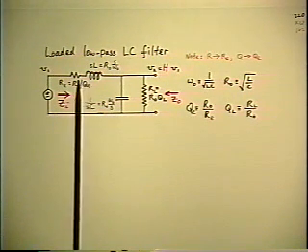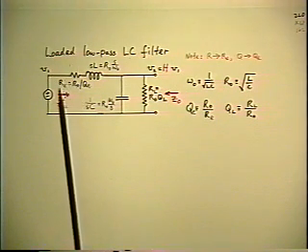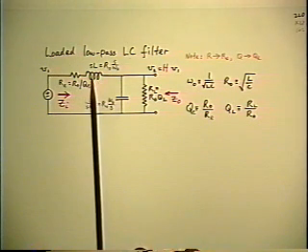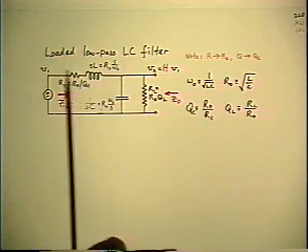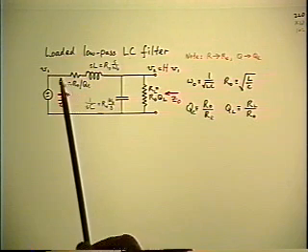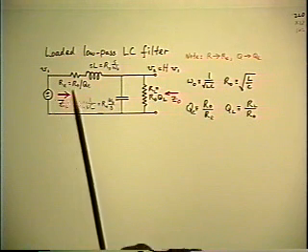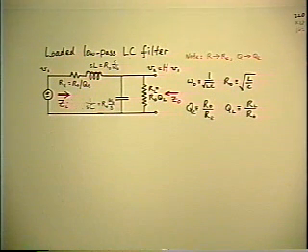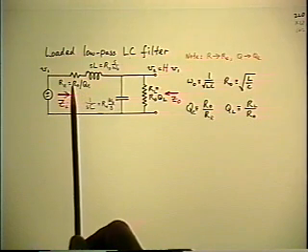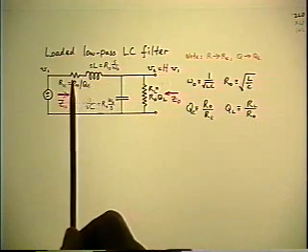The reason for choosing the subscript is that it stands for effective. Again, because in a practical case, this resistor is probably not a discrete resistor, but it probably represents the winding resistance of the inductor, plus possibly some source resistance, and in the case of a switching power supply, it also includes some sort of averaged value of the switch and the diode on resistances. So its value is actually an effective combination of maybe a number of contributions. From the switching power supply point of view, the objective is always to keep the total as low as possible, because it represents efficiency loss. The load current has to flow through that resistor.